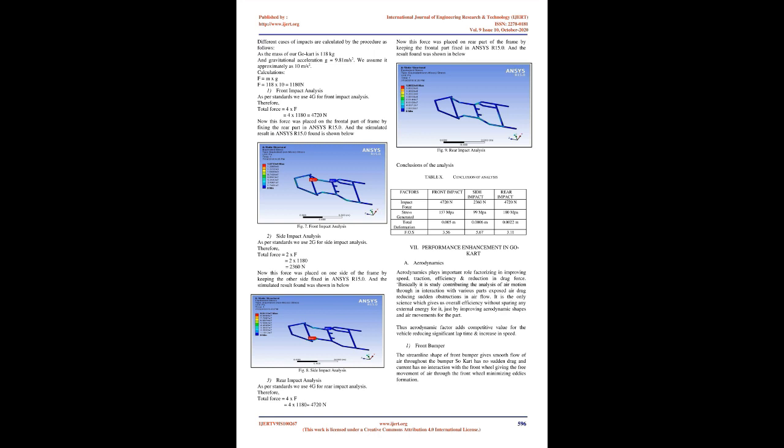2. Side impact analysis. As per standards we use 2G for side impact analysis. Therefore, total force equals 2 x F, equals 2 x 1180, equals 2360 N.